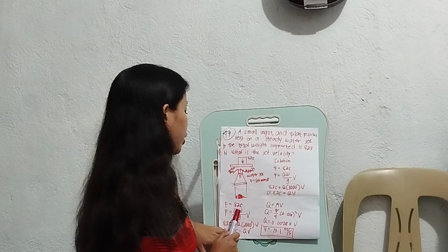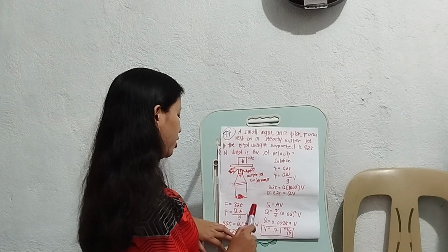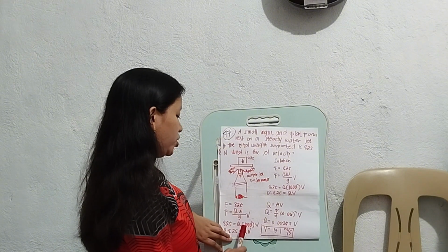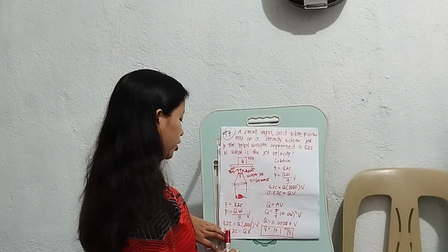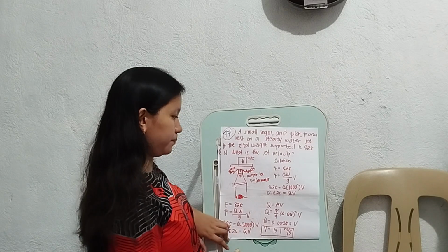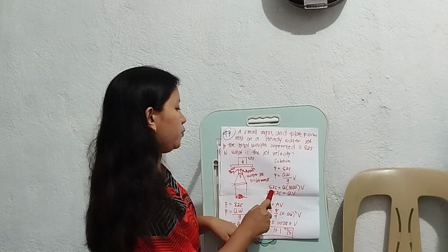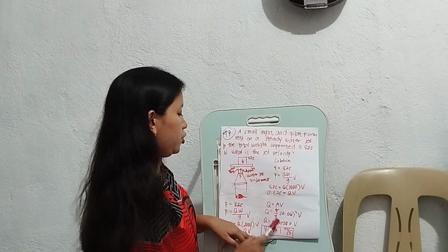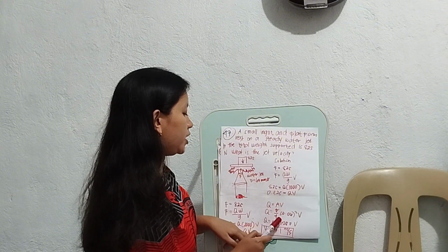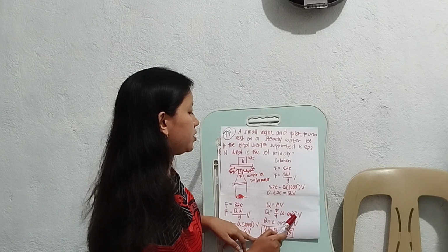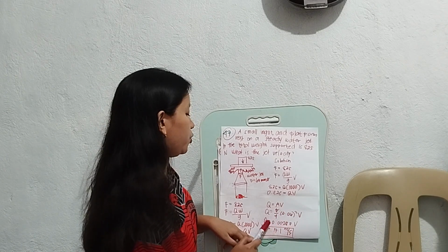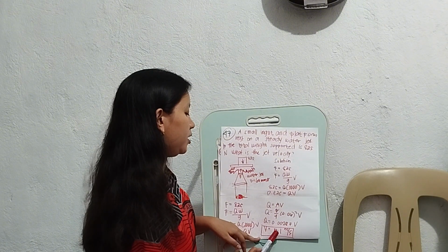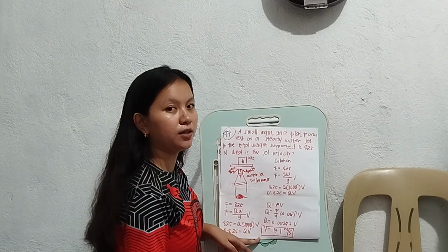So F equals Q times W over g times the velocity. Then F, 825, equals Q times the weight, which is 1000, times V. So 0.825 is equal to QV. Q is equal to AV, and the area is pi over 4 times 0.06 squared times V. So Q is equal to 0.0028 times V. Then the velocity will be 17.1 meters per second.